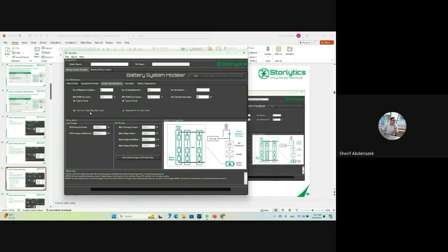So that's really important. And then here you have the ability to source auxiliary load from a separate feed. When I turn this on, auxiliary load in this diagram is connected to the grid from a separate point of interconnect other than the project's. If I turn it off, auxiliary load is being fed from the same point of interconnect of the project.